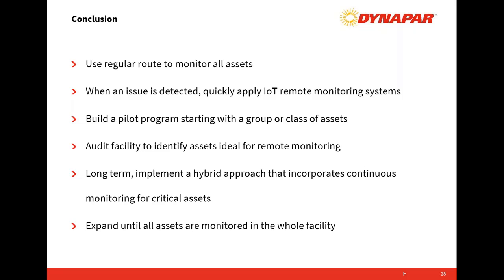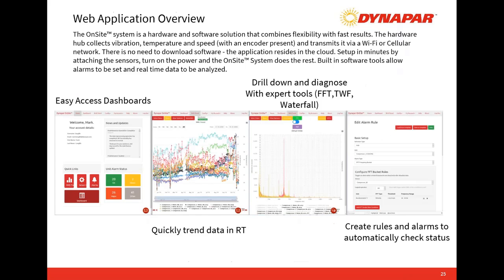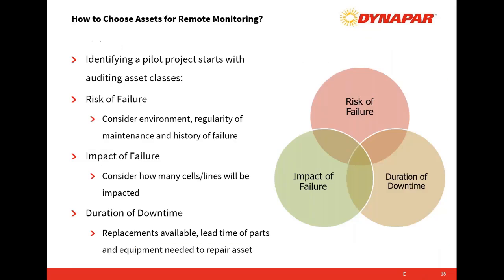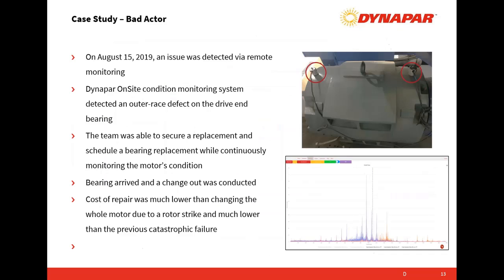They're digital MEMS accelerometers, and we obviously want to get as close to the bearing as possible. We want to eliminate anything that's hollow. We want it to be on a solid surface, but we would attach it at all 4 points of an asset. Let's say we have a motor and pump. We can attach either with a magnet, you can stud mount them, or you can epoxy pads on and bolt them in as close to the bearing as possible.